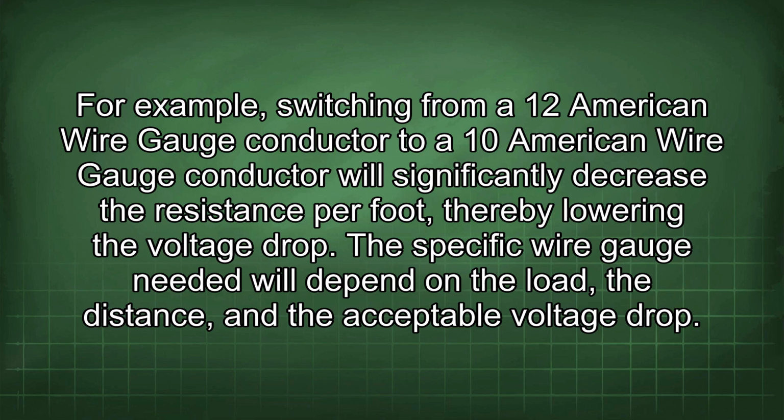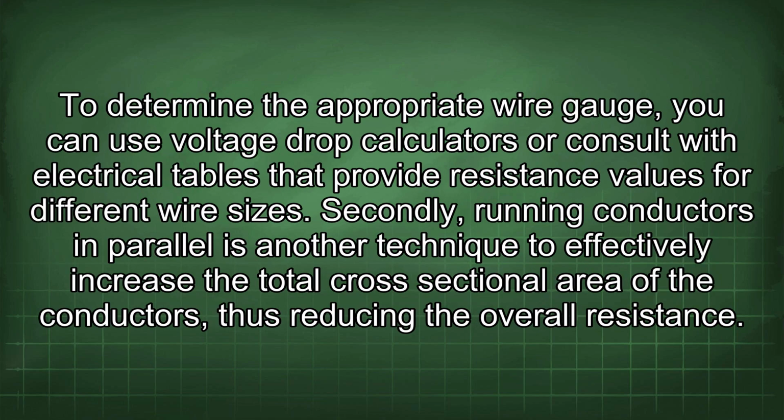The specific wire gauge needed will depend on the load, the distance, and the acceptable voltage drop. To determine the appropriate wire gauge, you can use voltage drop calculators or consult with electrical tables that provide resistance values for different wire sizes.